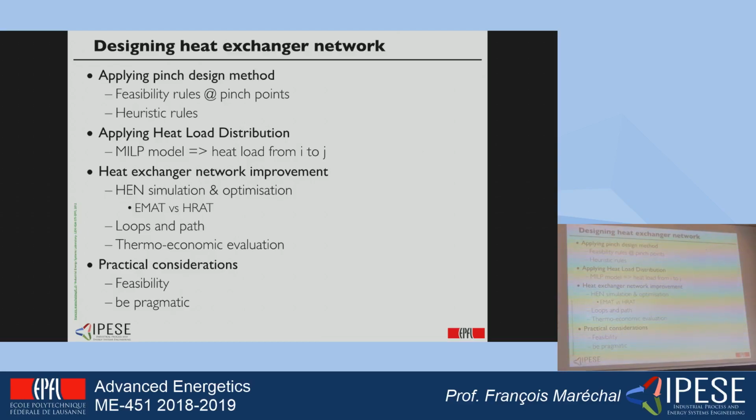the design of the heat exchanger network, mainly applying the pinch design method, which is based on feasibility rules plus heuristic rules. Something that I have not mentioned in the course is that there is also the possibility of applying mixed integer linear programming models to decide who is connected with who. But at the end, the two systems result in a heat exchanger network design, and we know that this one